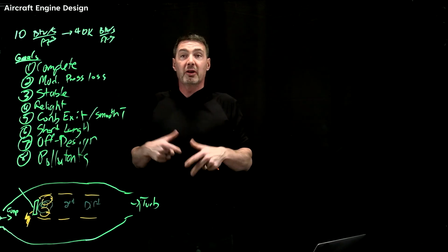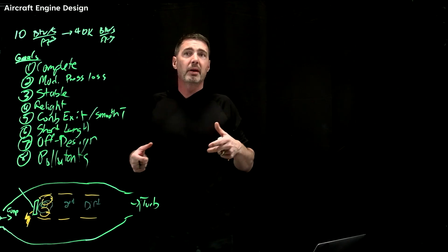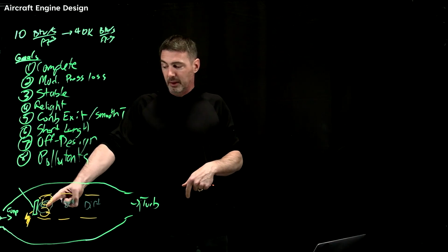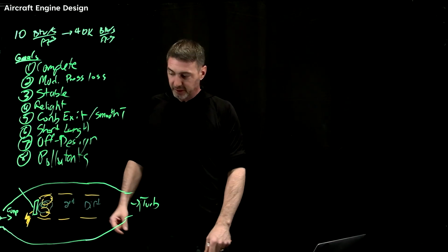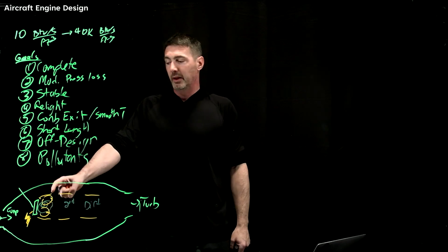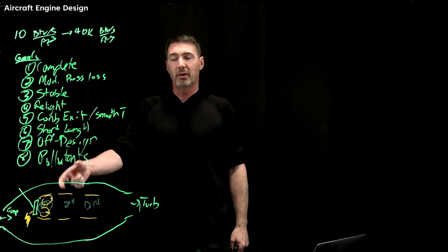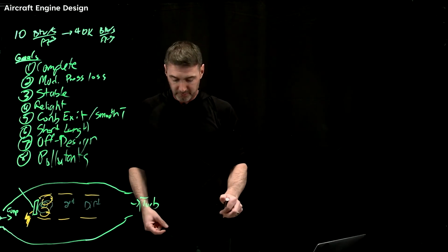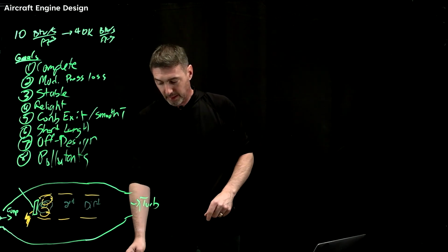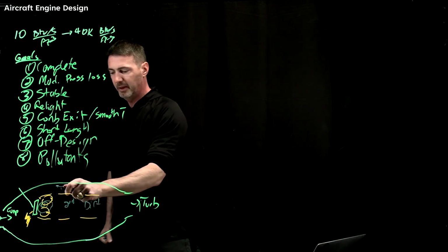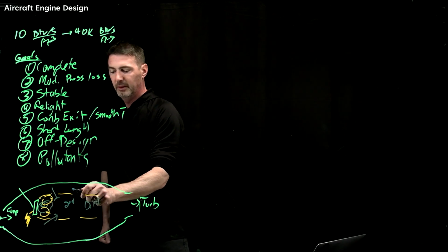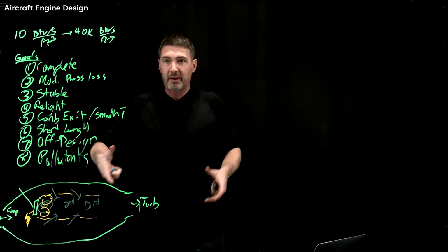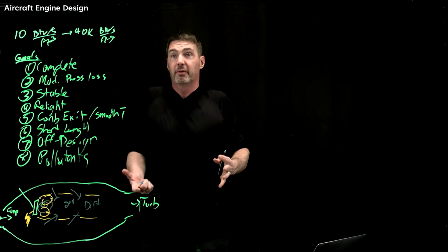And really, you're looking for, usually it's a laminar flame, which means a very smooth flame. Very different than a turbulent flame that's got all these fluctuations. So laminar flame, usually you do this fuel rich, okay? And so you're going to do fuel rich to have good stability, all these different things, but then the air that's coming around it, you're going to quench it lean ultimately over here for emission control. But throughout this, air is going to come in through these slots. So it's going to come in to these dilution holes, but it's also helping keep this combustor liner from melting again.